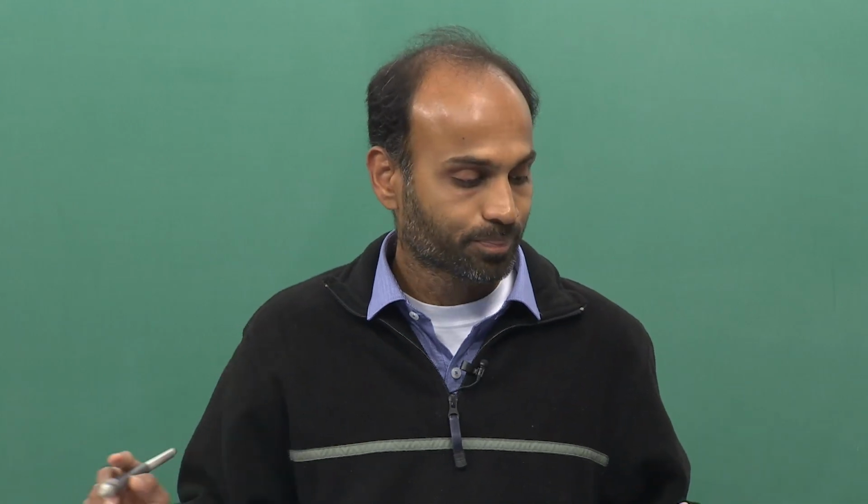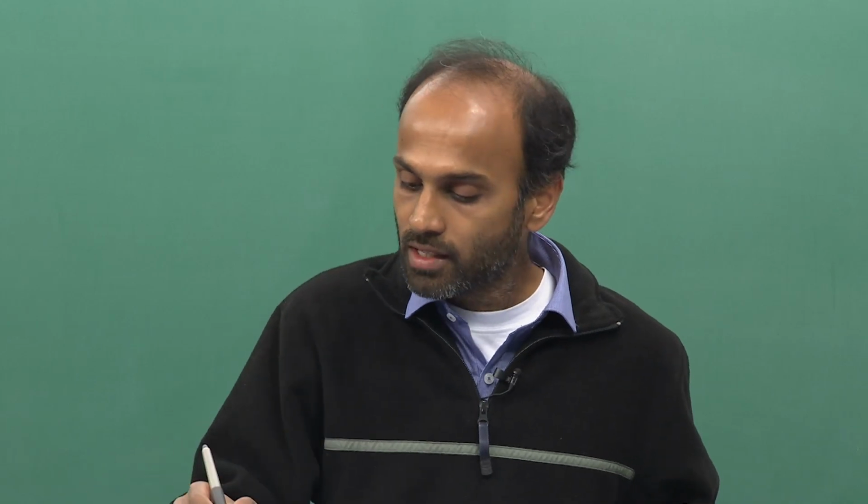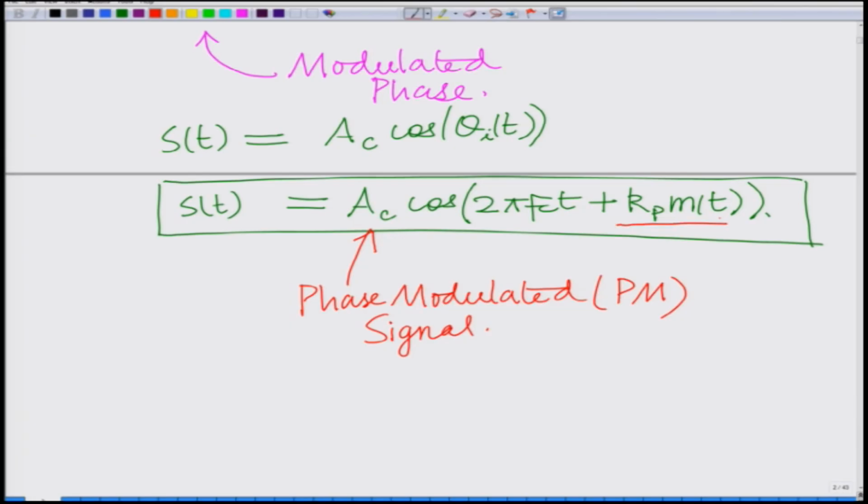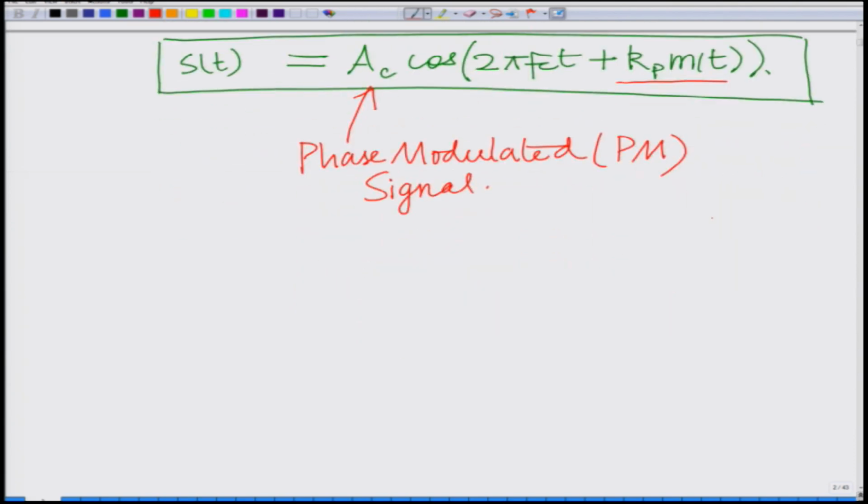Because the phase is modulated by the message, if the message has a discontinuity, for instance if the message is a step function, then the phase of the modulated signal experiences a discontinuity. This gives rise to high frequency components.